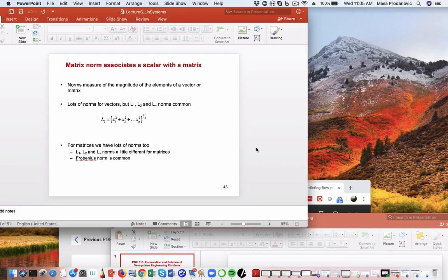Okay? If you remember the system where we had the model of the heated rod, the middle of the system is basically related to that heat transfer coefficient H out of all of the nodes towards the air, whereas the boundary conditions, the temperature on one end and the other end, were playing into the right-hand side.